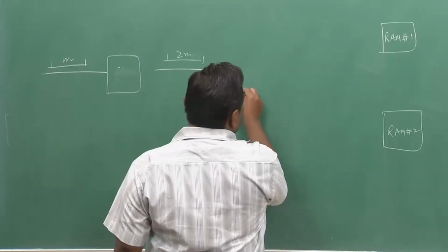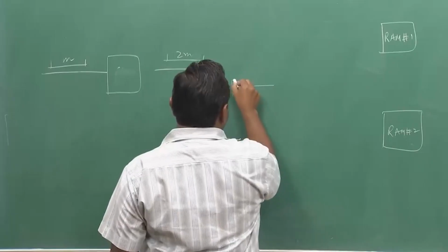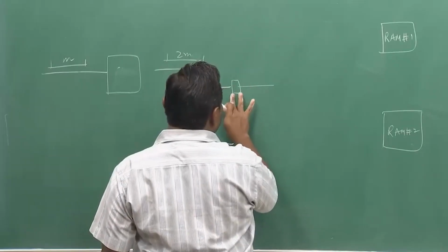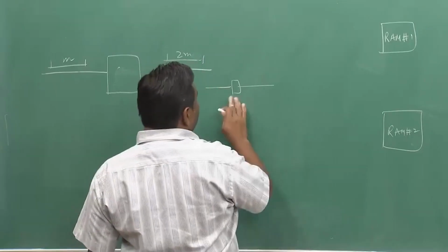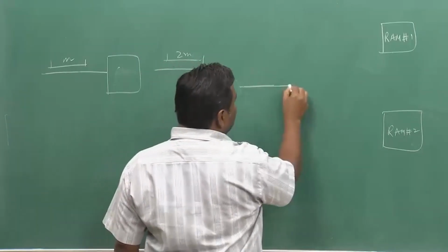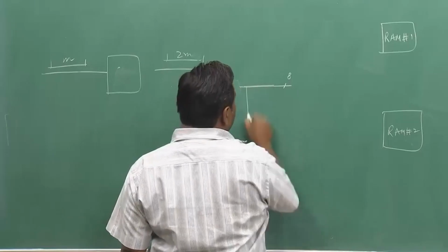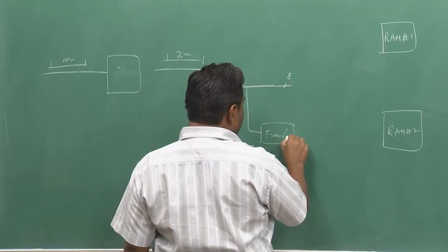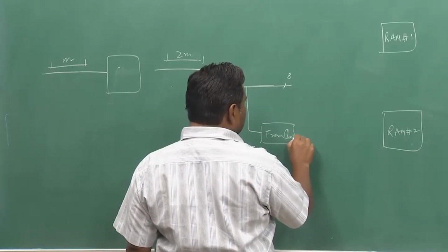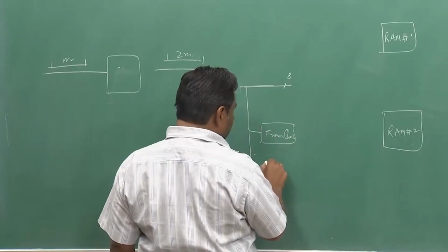So you will have a signal coming in, and obviously you will be getting a serial TDM stream. So you will be doing parallelization. I am assuming you get a parallel stream out, and you have already got the frame clock from here. This is required to reset the counters as we had done earlier.